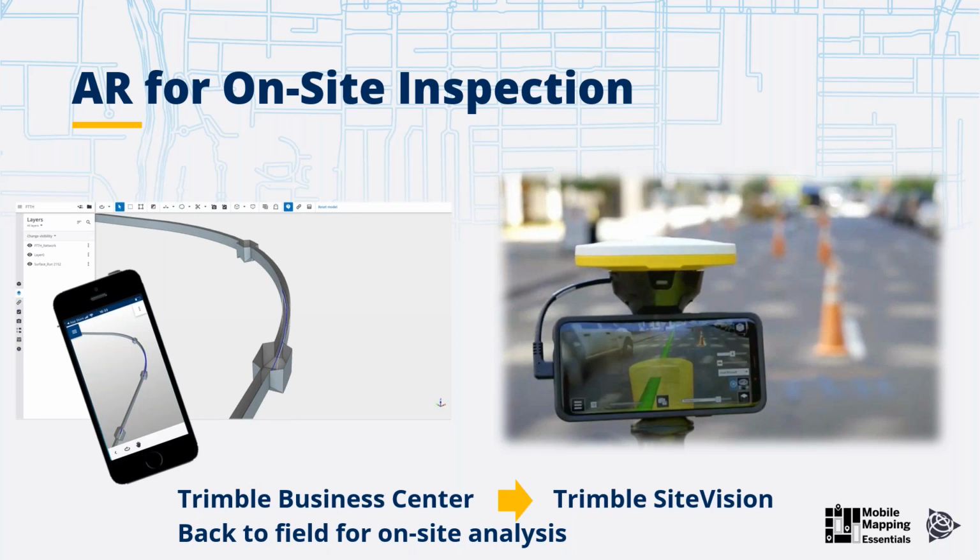And once this model is on the SiteVision, the operator has the chance to do measurement of mesh against reality, or maybe measurement of mesh against GNSS position, because the SiteVision kit is also equipped with a GNSS antenna, so you can also make RTK GNSS measurements. And so from this point of view, the SiteVision can be the final step, the last mile, if you like, of the workflow where you can really see how your project will look like in the field, right?